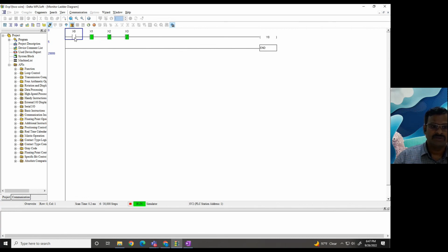And here the temperature, if it reaches the minimum limit, then the boiler output, the motor which will take the water from the boiler, will enable. So this coil is getting enabled, and the water is going to the next stage. In case the water level decreases to a certain extent, this contact will open, and when it is open, automatically the system will go off.